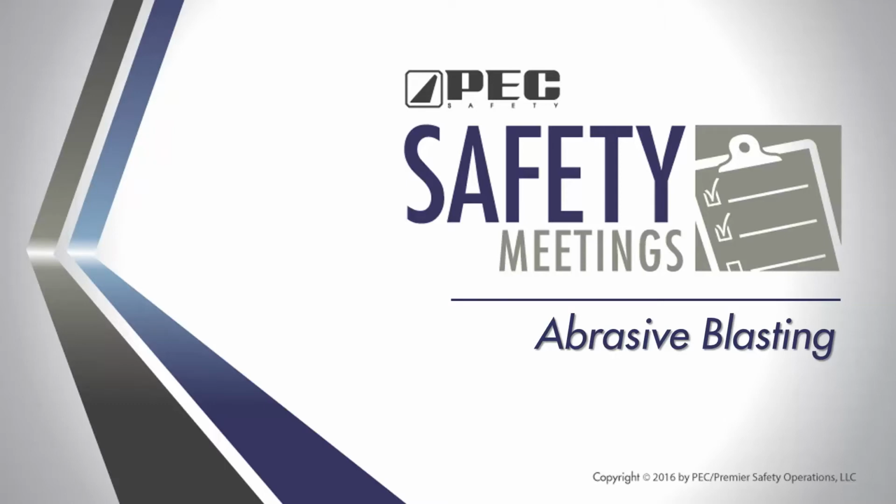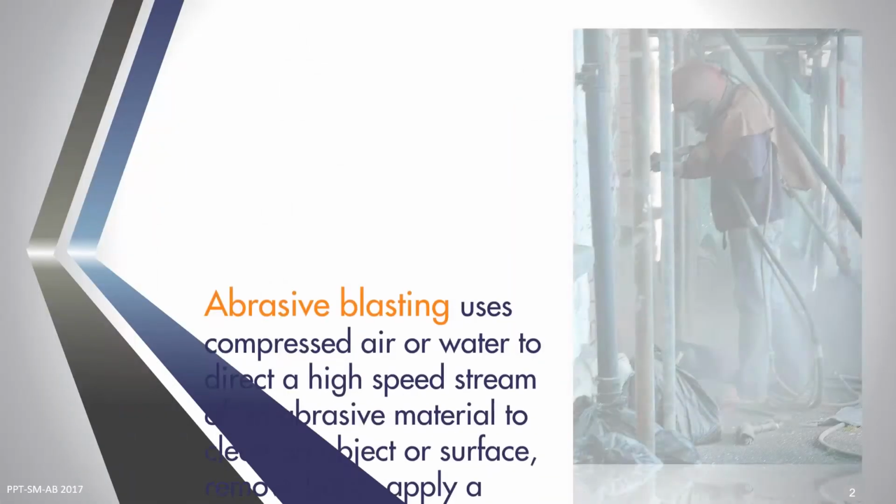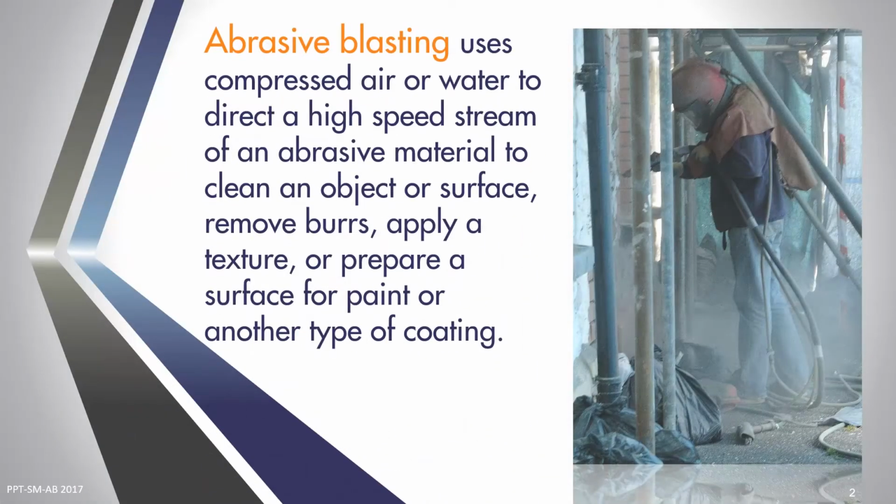Abrasive blasting. Abrasive blasting uses compressed air or water to direct a high-speed stream of an abrasive material to clean an object or surface, remove burrs, apply a texture, or prepare a surface for paint or another type of coating.